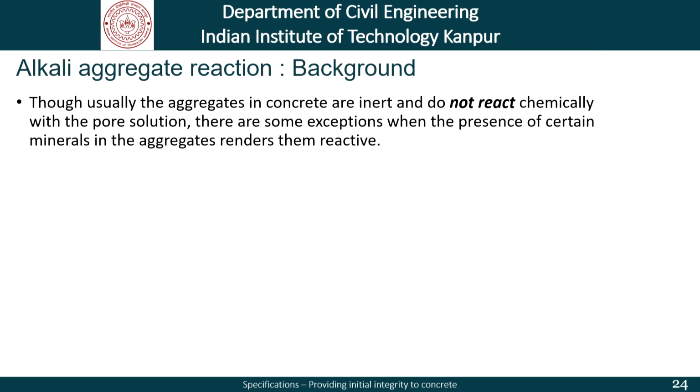Moving on, we go to another mechanism, which is alkali aggregate reaction. Usually, aggregates in concrete, whether it is sand or coarse aggregate, are inert and do not react chemically with the pore solution. The exception is alkali aggregate reaction, where the presence of certain minerals in aggregates, whether sand or coarse aggregate, renders them reactive.